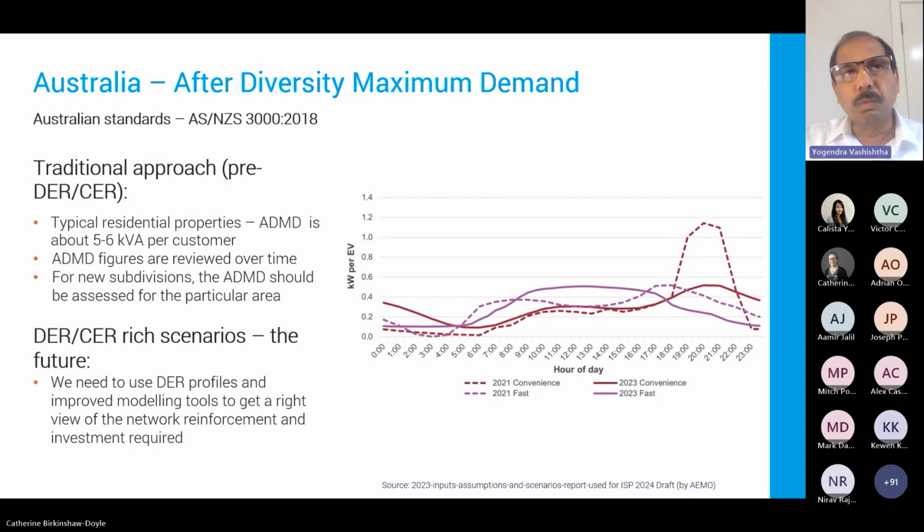So what happens is that for EVs, I've seen people using 2 methods, like calculation and limitation. So they're saying, okay, we have been given 63 amps with an 80 amps fuse. Now, if we are using 7 kilowatt, that means this 32 amps load, then we have to add this 32 as it is, like for smaller EV things. And the second method can be limitation, that we can limit the load.